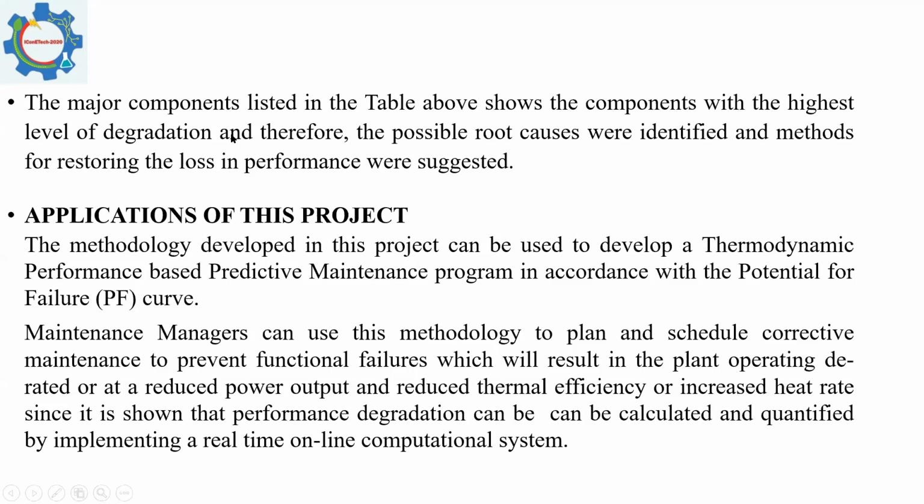And the same applies to every single component. They give you an overall performance, overall plant performance in terms of power output, efficiency or heat rate at, let's say, basically ISO conditions, and you have to determine what your design performance will be at site, because of course your site condition is different from ISO.